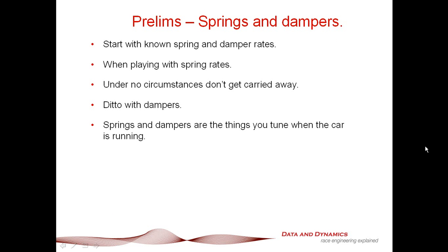Prelims, springs and dampers. First things first, you start with known spring and damper rates. You don't get carried away. You don't get any brownie points for getting really clever. I really want to ram that point in. A lot of what you'll wind up with for spring rates isn't just dictated by ground clearances. It's also dictated by what the tyre wants as well. So at this stage of the design process, don't get overly carried away with making your springs massively soft or massively stiff.